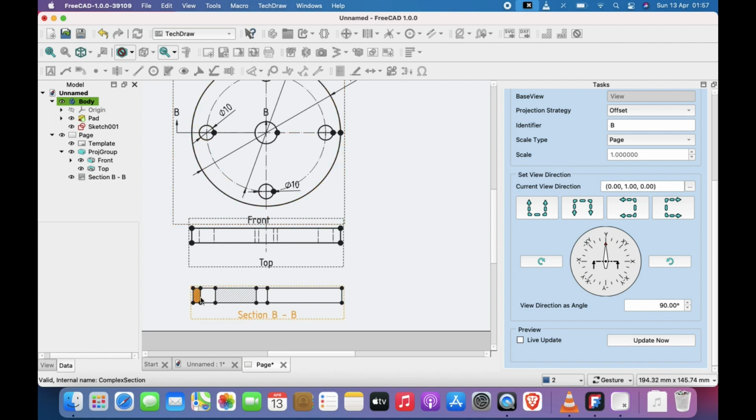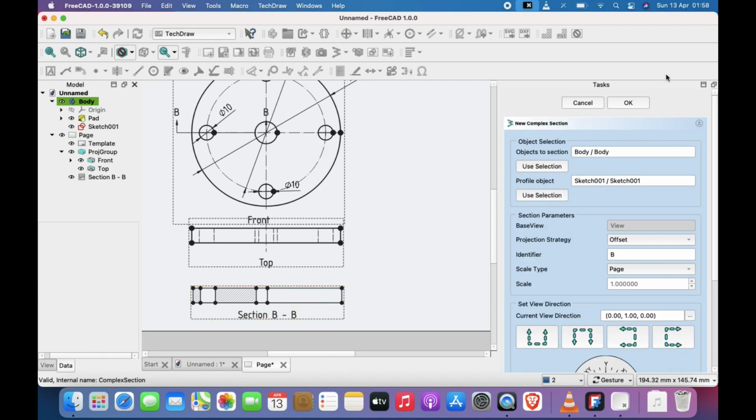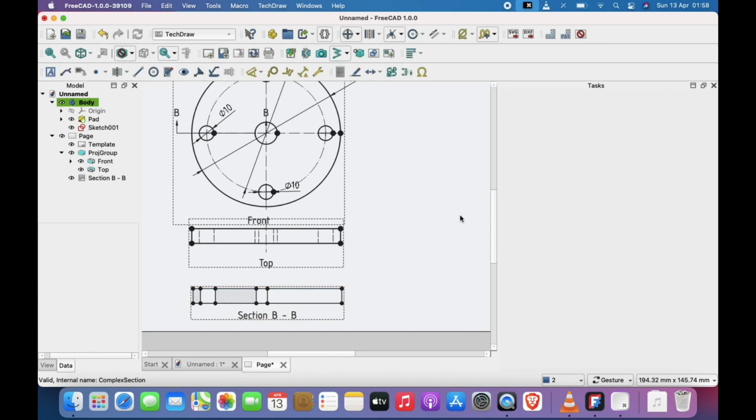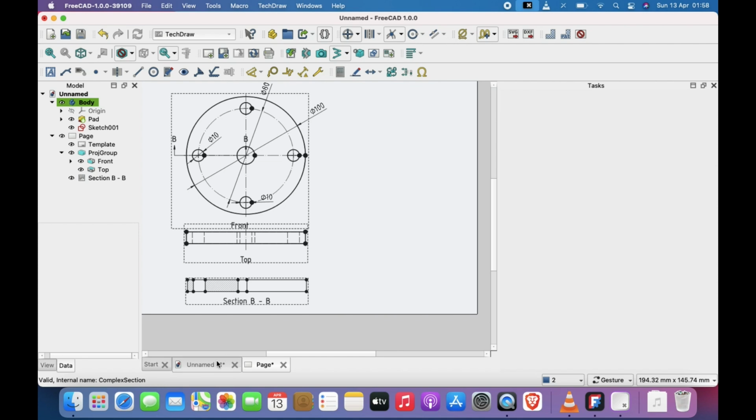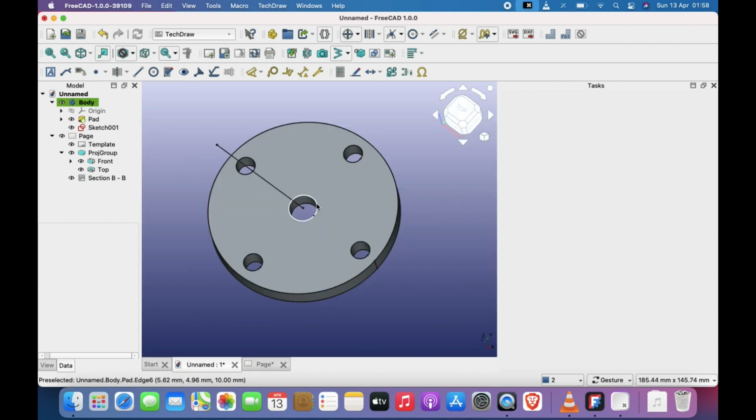So this is arched, and then I can see the entire inside here. It doesn't need to be arched. Then it cuts through this part here again, and this is arched, and then it ends here on this line. So that's what this line indicates. And I'm just going to click on OK, and that's it. That's really it. That's how to create complex sections. So now your sections can be as complex as you make the line to be.